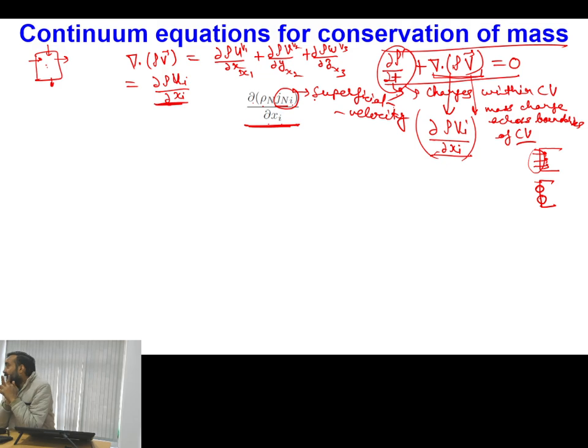But in case of multi-phase flow, at the boundary there can be some portion of other phases present. So the boundary of a control volume is not completely filled with the nth phase which we are referring to. So in order to take into account the difference between the phase velocity and the superficial velocity, because superficial velocity, despite the phase fraction, only accounts for mass flow rate over total area, that's why I am using j n i over here. Is this point clear or not?